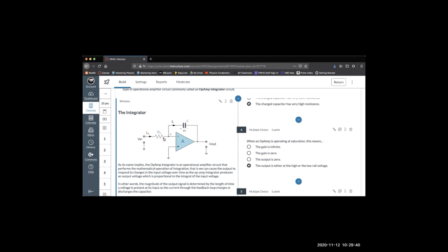And in our simulation, just like in this diagram, it doesn't show the voltage connections. But an op amp has to be powered to work. And the maximum possible output voltage that an op amp can have is the maximum voltage that you supply it with. Right?